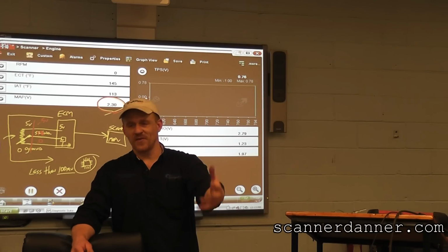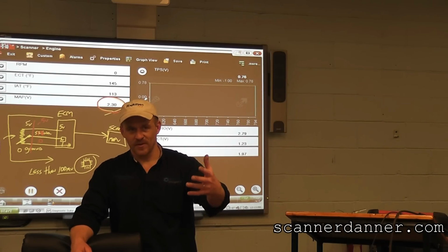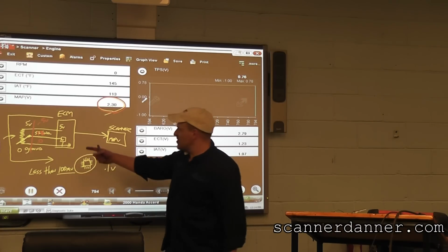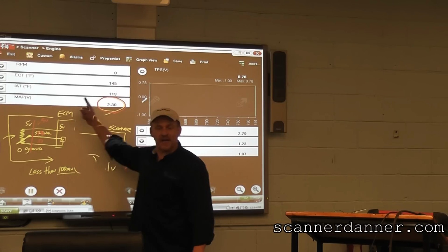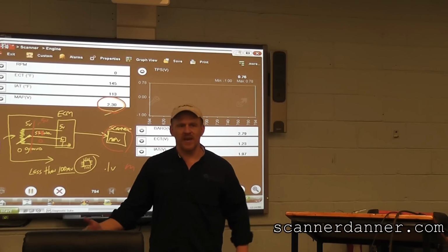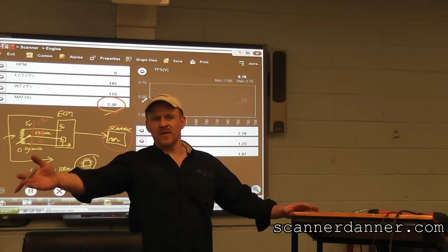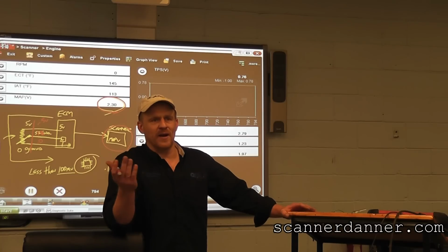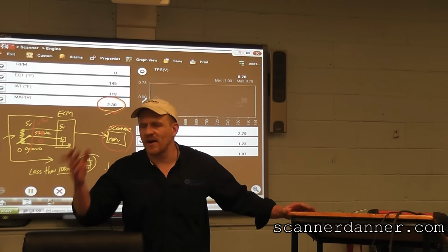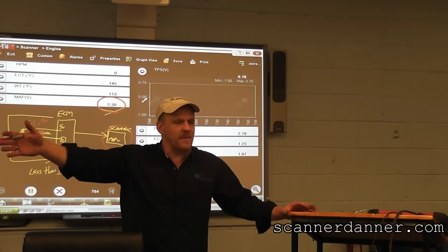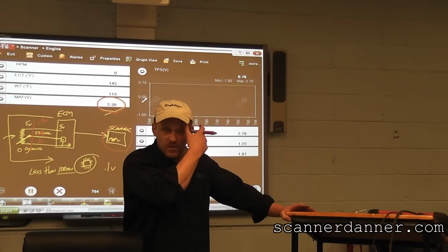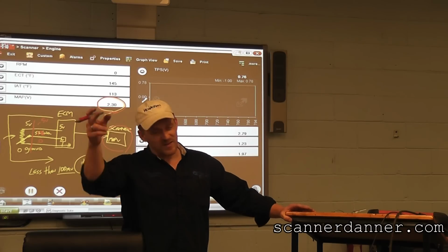Now, herein lies variables. I mentioned a couple. Sometimes you need an RPM signal for a data PID to change. So you're down here manipulating the circuit looking for a data PID to change over here on processed data, and the computer program is saying, I'm not changing that PID because nothing's happening right now. Why would I update the MAP data PID when the car's not even running? I already got my baro reading. I'm not even looking at that MAP sensor right now, if that makes sense. That's why I left the car run. Needed that RPM signal.